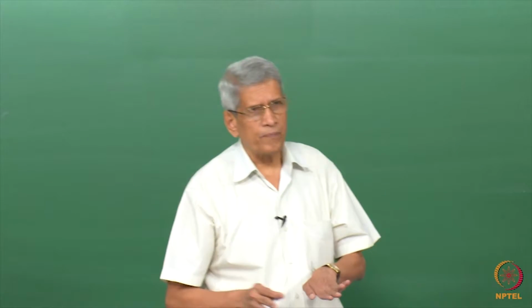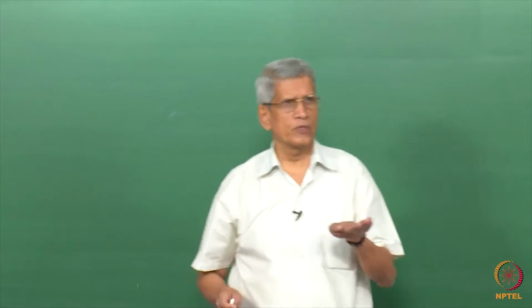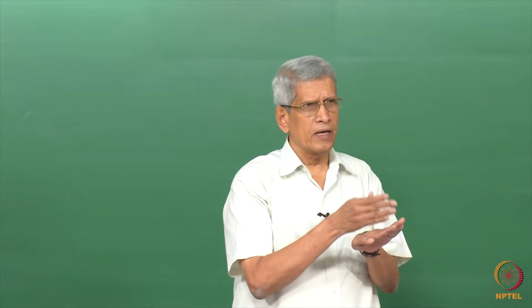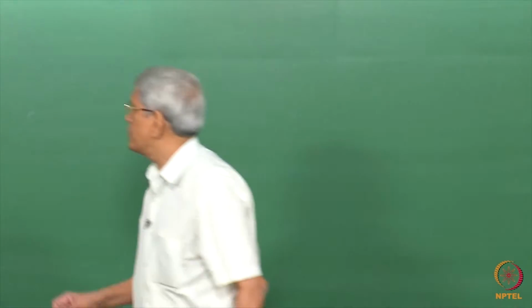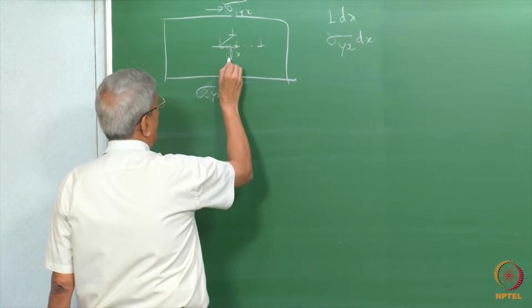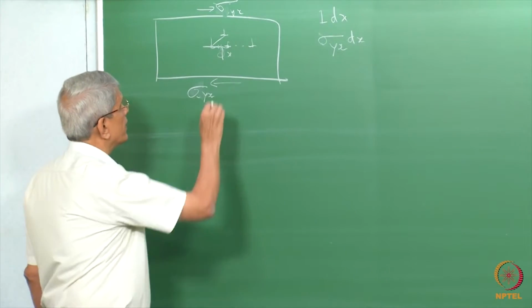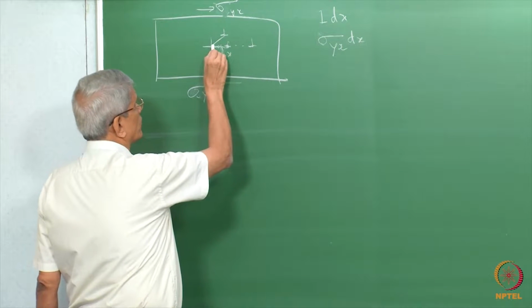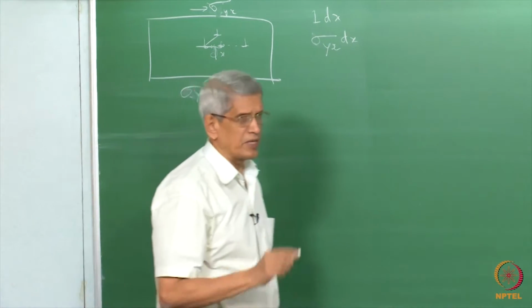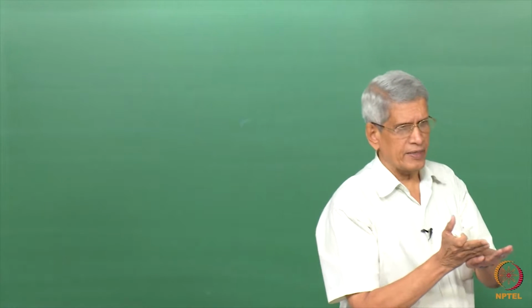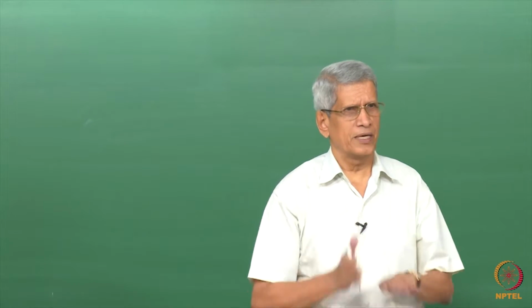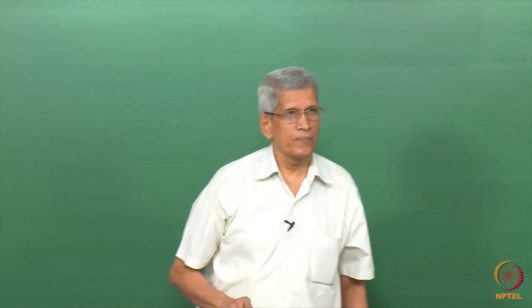But whenever any dislocation moves, it displaces every atomic layer by a Burgers vector. That means if it has moved from here to a position here and this distance is dx, this much layer which was originally at some position has been displaced by a Burgers vector, always. Each layer has moved, shifted by a Burgers vector. So that is the displacement.